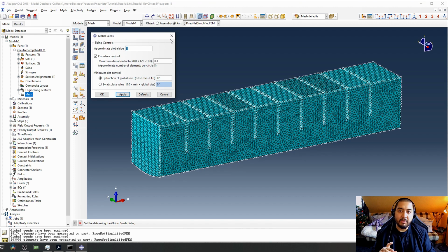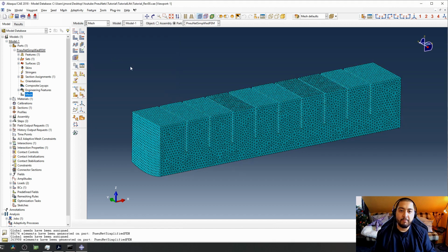we need to decrease the global size. With this global size of 1, I personally recommend at least 20 gigs of RAM, because the process to solve this setup is going to take 16 gigs, plus your operating system, plus any other background process that Windows is always executing, which is going to take more space.